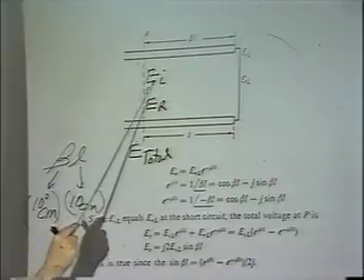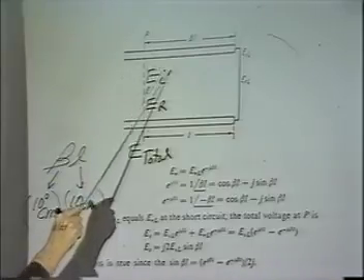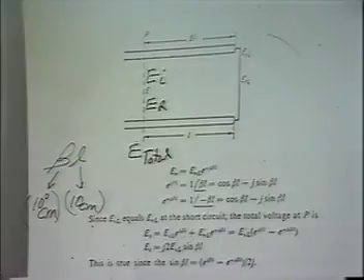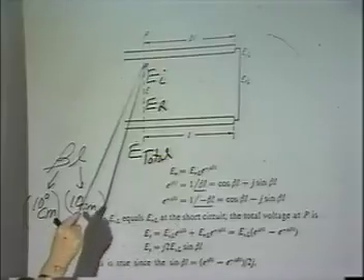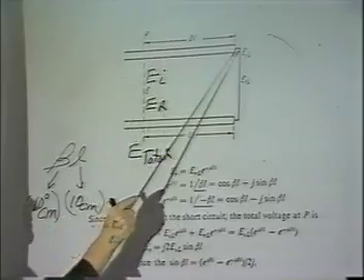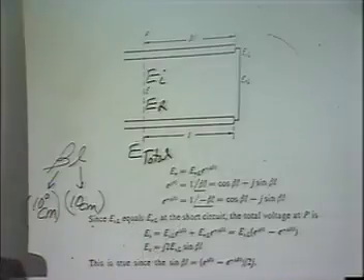I can say this is E sub I, e to the j beta L, which is this function over here, which says that this voltage is here, and that it's going to be over here 100 degrees from now. You can calculate that in terms of time if you know the frequency and so forth, right?